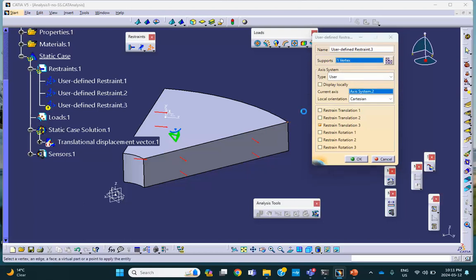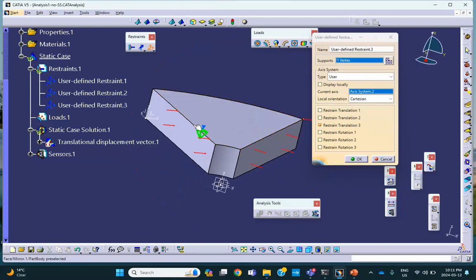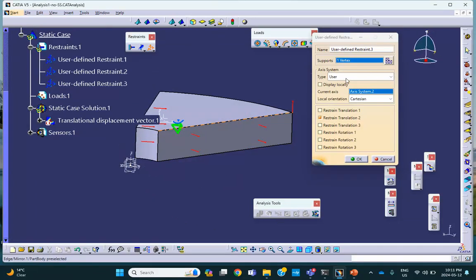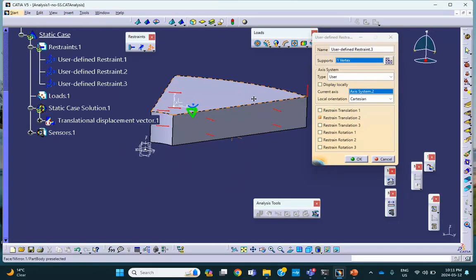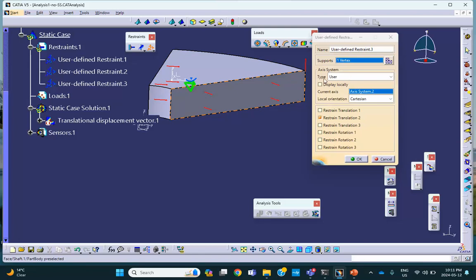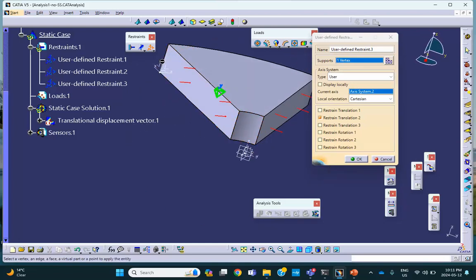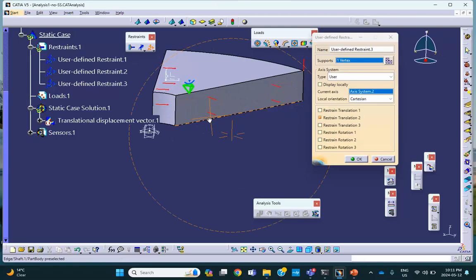The coordinate system is user. If you're using user, notice that upward is Y. So it's not this one, but it's this. If you're using global, it would have been third. So just be careful because it just happened that user was active. And if our user is active, this point cannot go in the vertical direction, which means Y in that coordinate system. Okay, so fine, run it,